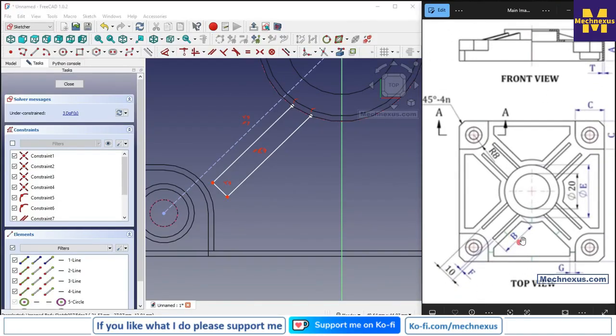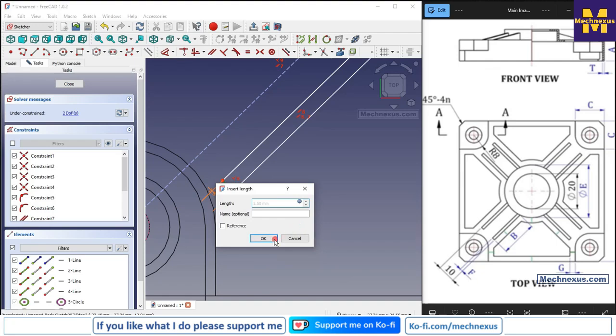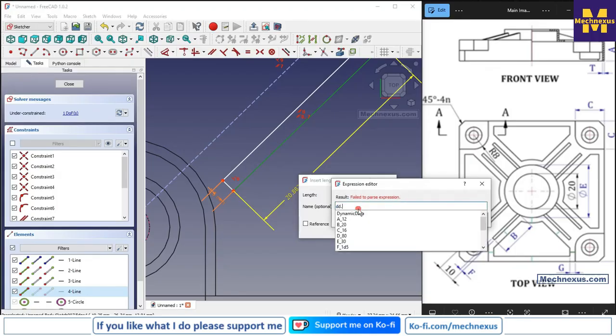Here we can see that the values are B and F. First we will link the F value, which is the thickness, and I will go here in expressions, type dd dot F is equal to 1.5, say OK, and then select this line, and this is B. I will type dd dot and the value is B, say OK.